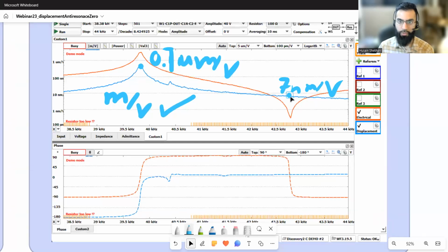As you get past the resonant frequency and add damping, your off resonance displacement is still relatively constant. The bandwidth starts to increase, the peak starts to decrease. So you actually get a little bit higher off resonance displacement in an actual application than the transducer just sitting in air. However, it will be very stable, this ratio between voltage and displacement.